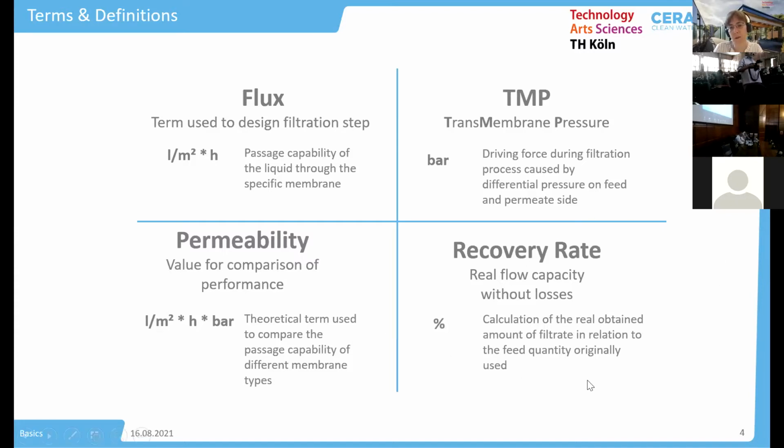Finally, also interesting is the recovery rate, which is a real flow capacity without losses. This means all the backwash water is already integrated in the recovery rate, and you have a calculation tool to see the efficiency of your membrane system.